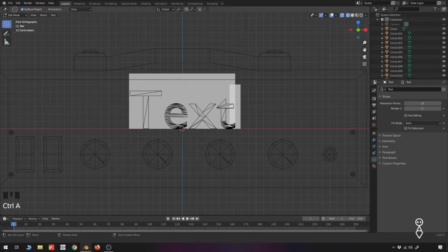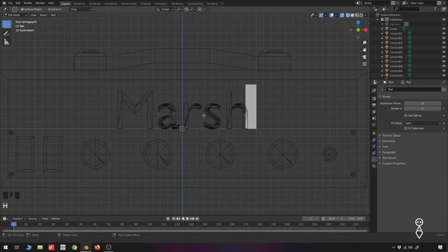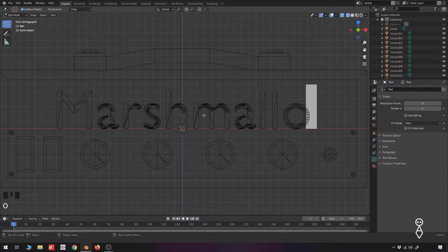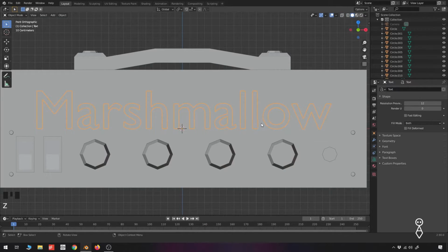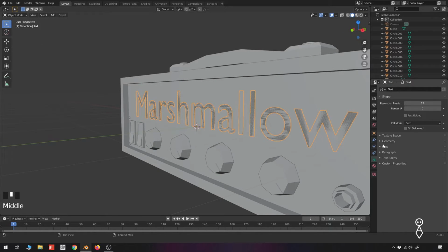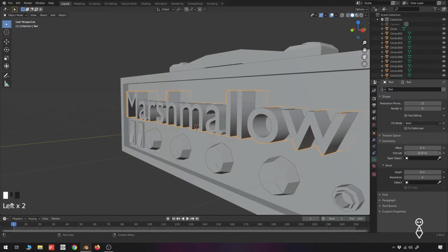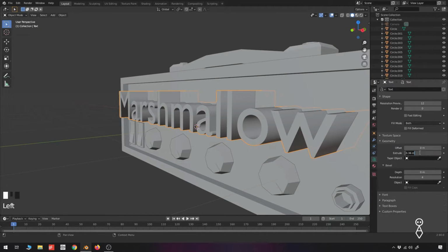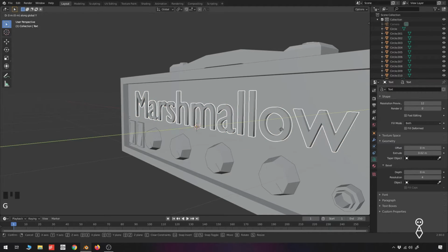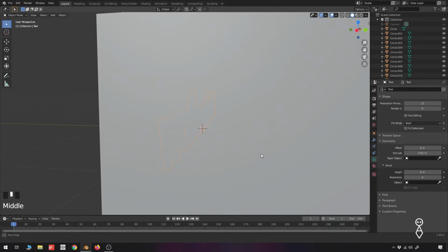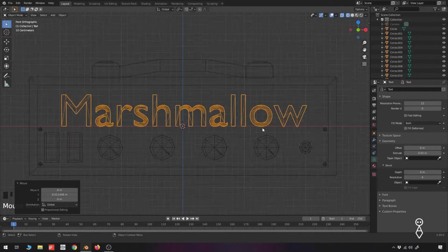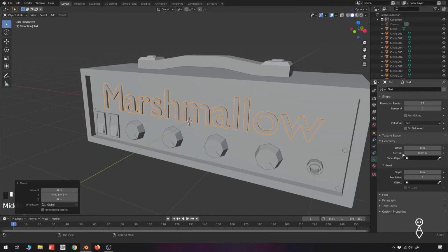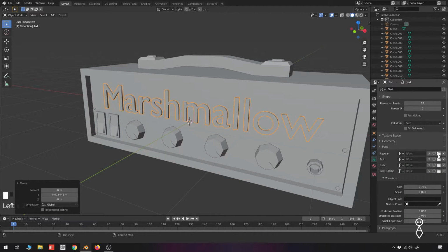Press Tab to go to edit mode and type in your new text. Extrude the text by going to Geometry, Extrude in the text menu. Under Font, change the font style. I used Lobster Regular in this example.